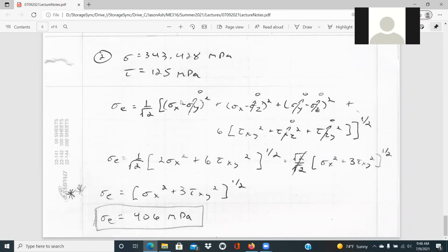And if we look at von Mises stress, this is a common loading condition where you have a pure axial torsional loading. And so if we look at that from the actual state of stress, where we have our sigma x term, our sigma y and sigma z are 0. Tau is our tau xy, and tau xz and tau yz are both 0. This simplifies down pretty well.